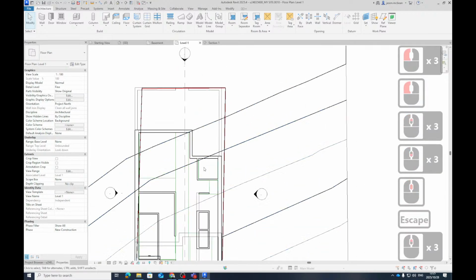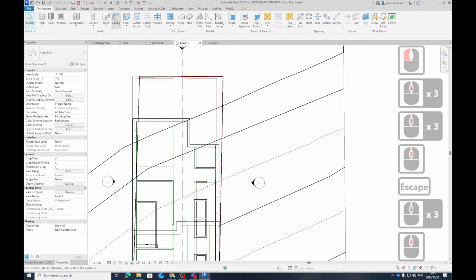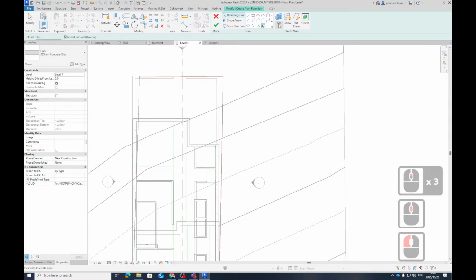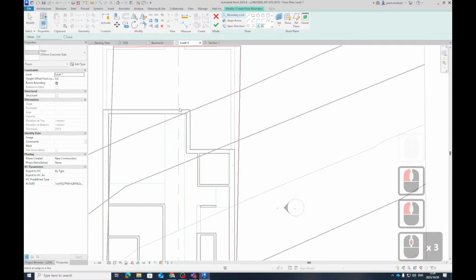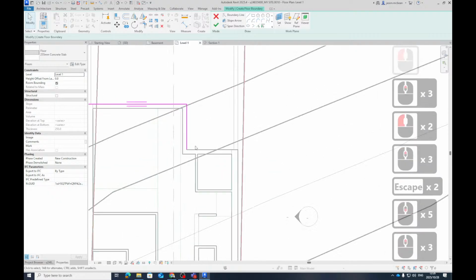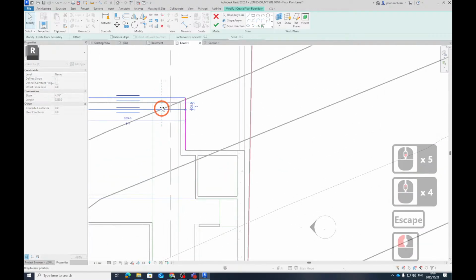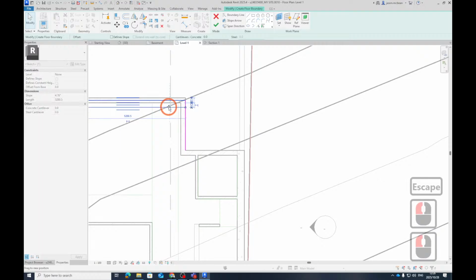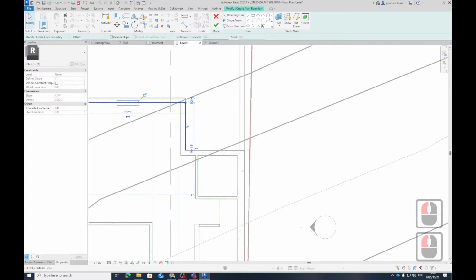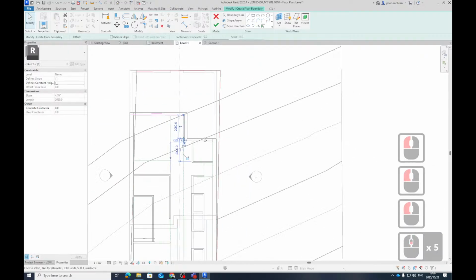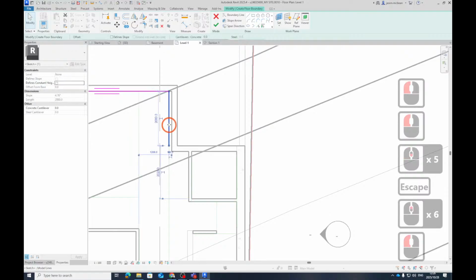Now, if I want to cut in again, I'm going to go to floor, and I'm going to use this very quickly because I want to say that's the outline of my floor. Sometimes we use the internal, the outside, it doesn't matter, but technically, I'll explain. I like to use this rather. There's a trick that we do. Technically your floor stops there and your basement goes past. So let's just snap this.